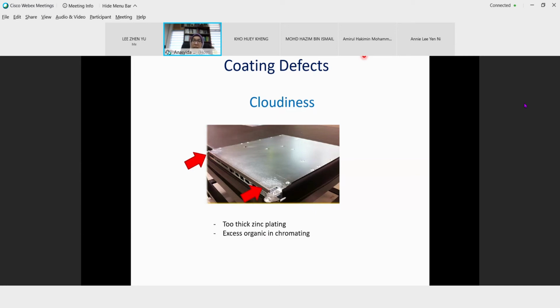Or it could be your process during handling. So you can look at the area surrounding the dent. If in the area surrounding the dent the size of the grain is not affected, meaning it's not deformed, so let's say you find the grain size surrounding the area is bigger, it means that it might not have happened during the incoming process.